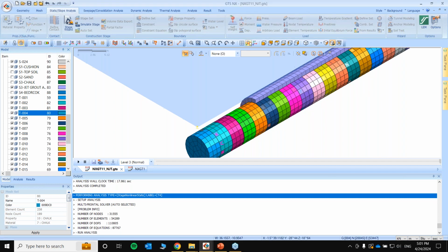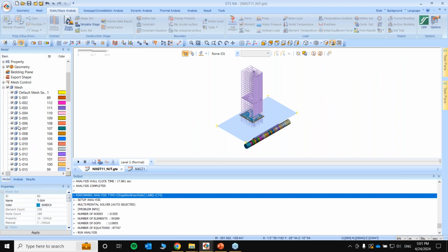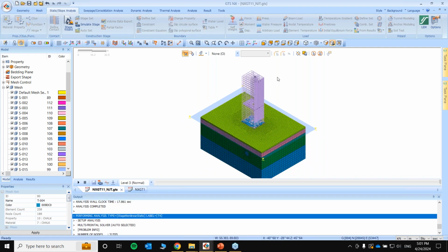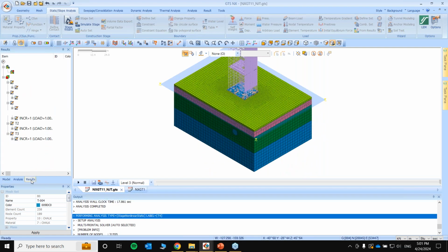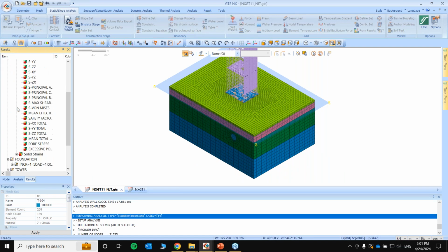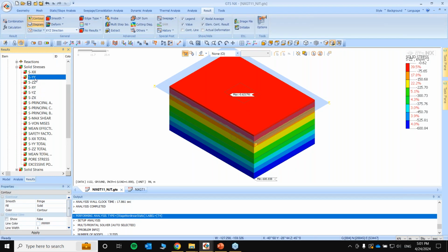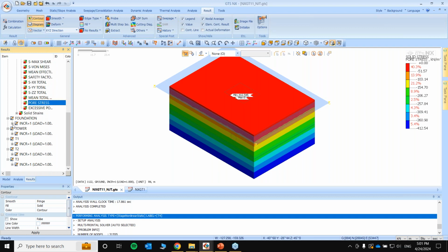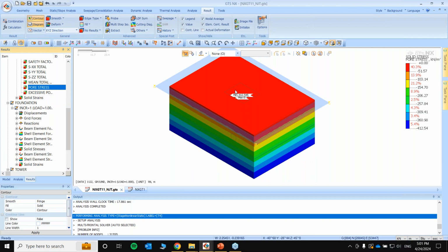So we will see now, first of all, the impact of presence of the building there, and then until the model reaches divergence. Go to results. In the ground stage or the initial stage, we'll only go for the ground stresses, the vertical stress, horizontal stresses, and then the pore pressure. In the foundation stage, we activate the cushion, the raft, and the piles.